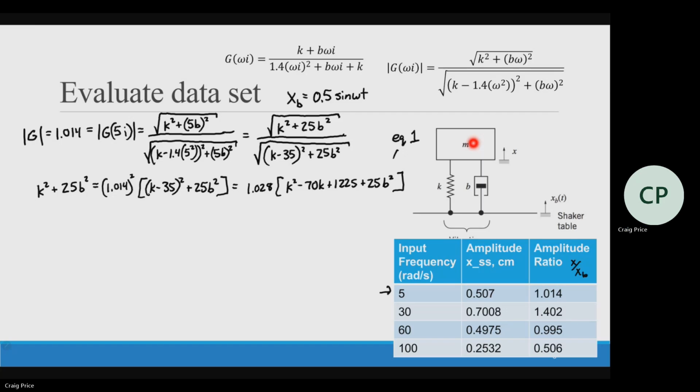Again, stiffness is pretty easy to find from a test. Damping coefficient is not. So having a test where we can change the frequency and change the magnitude effectively, from there we can calculate what those B and K values should be. So we would do the next one.